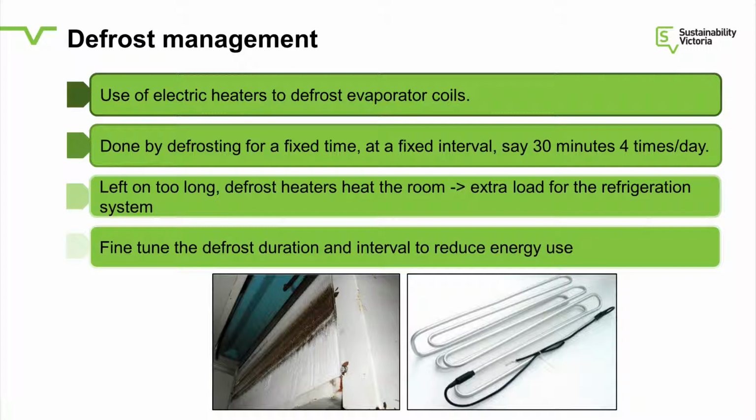And it varies from one room to another. Rooms that are constantly people going in and out, well, maybe half an hour every 4 hours is not even enough then. So it is something that needs to be observed and fine-tuned for every application. So if it's too long, you get the extra load. If it's too short, you get a build-up of ice over time, and then the defrost doesn't even work anymore. Then you have to really do a hard defrost, go in there with a hose and get all the ice off. So fine-tuning it is something that can be done.